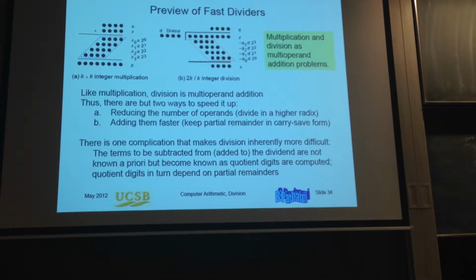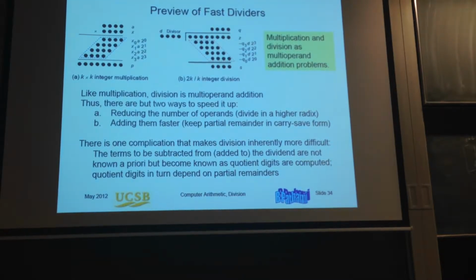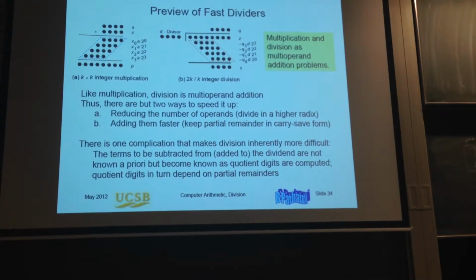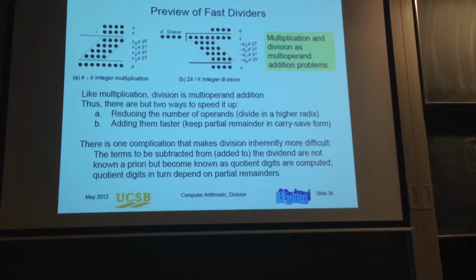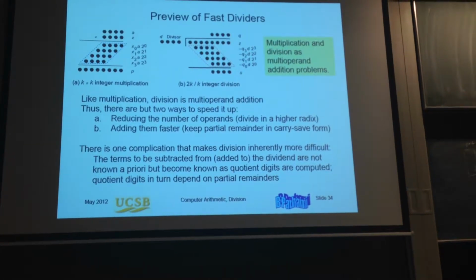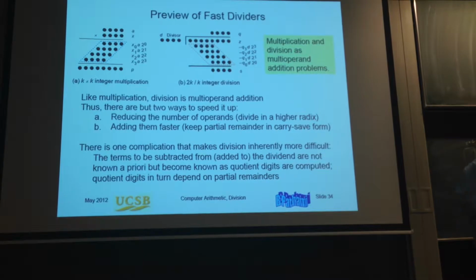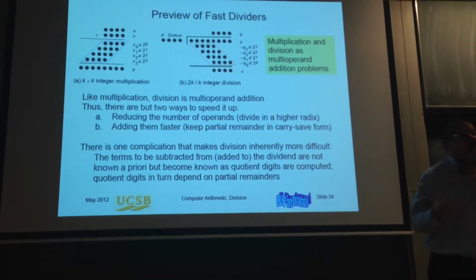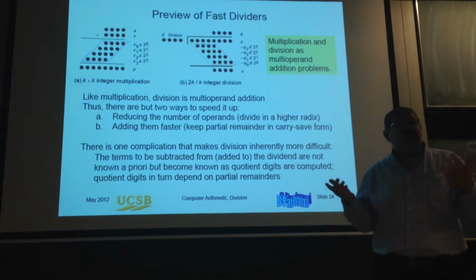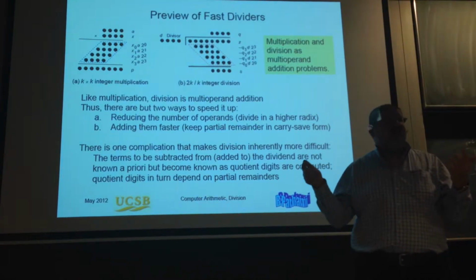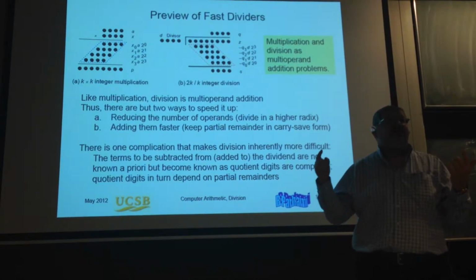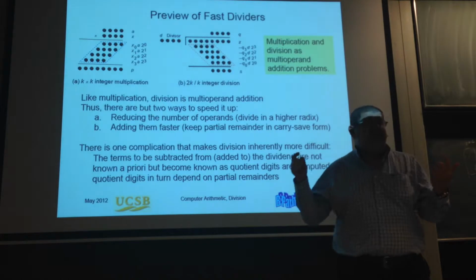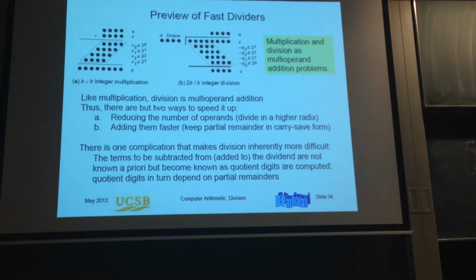The same story can be done here, but there is a small difference, which is essential. Not the fact that the partial product matrix for multiplication is like that, and for division is like that, even though the story is coming from there. It's from the fact that there are dependencies, and the quotient digits can be guessed only in a sequential way. And this is creating the problem.